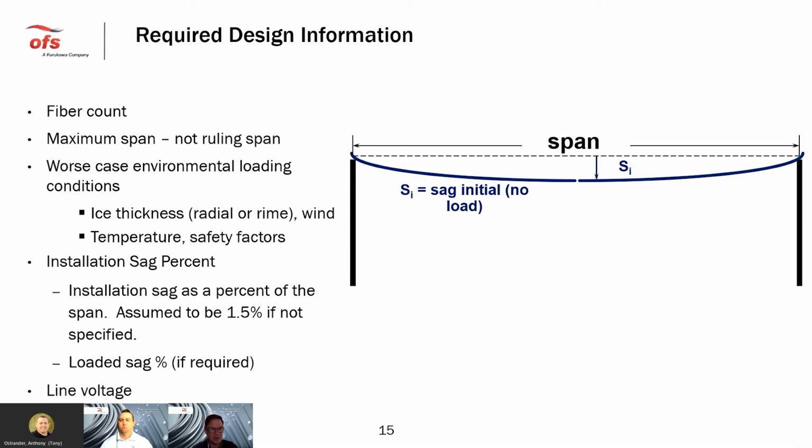And then also we can design the cable to actually be installed and operate within a window. And so the more aramid we use, the more stretch we can avoid under loads to actually give lower sags. And so that's something we can actually control. And the final thing is line voltage. In distribution lines, we typically use polyethylene, but when we get into higher transmission voltages, then we can get into the use of a tracking resistant jacket. So that's some background around ADSS.